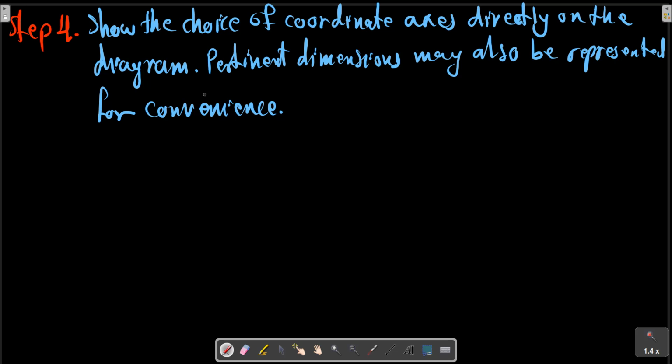Note, however, that the free body diagram serves the purpose of focusing attention on the action of external forces, and therefore the diagram should not be cluttered with excessive extraneous information. Clearly distinguish force arrows from arrows representing quantities other than forces.